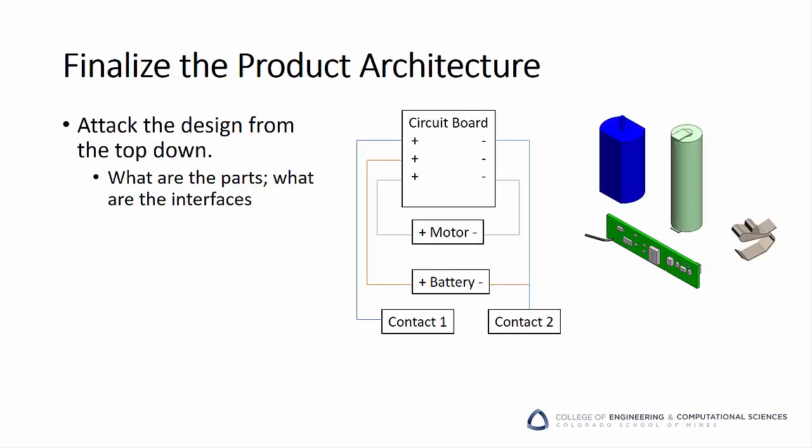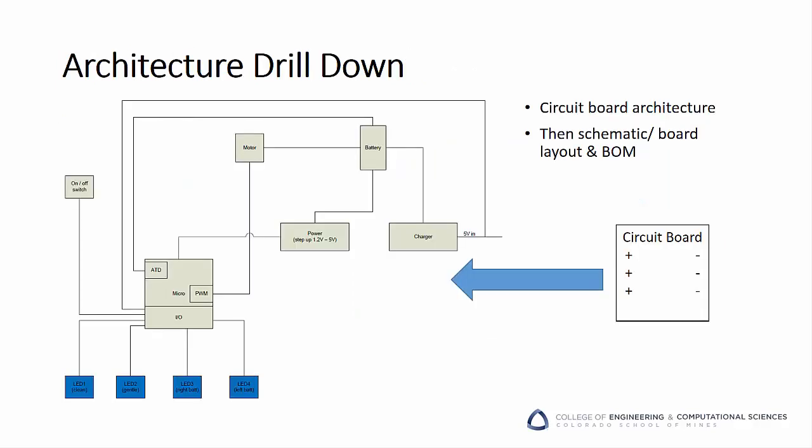Something as simple as this rough architectural diagram of the toothbrush side electronics helps allow the team to begin labeling voltages and delegating the selection and testing of batteries, motors, and the like. You're peeling away the design one layer at a time. With the top-level architecture agreed upon, now you start figuring out the circuit design, defining the overall architecture first. Finally, you get to board layout. If you skip straight to board layout, you'll waste tons of time and miss things that should be obvious. Luckily, this process only applies to electrical engineering, right? Wrong. This holds true for every discipline.